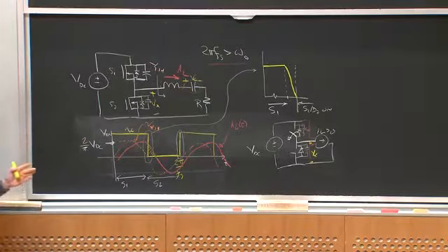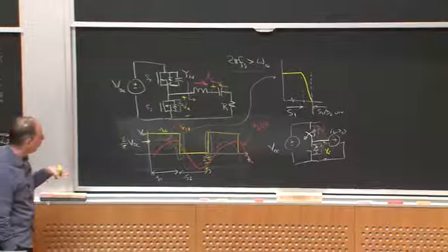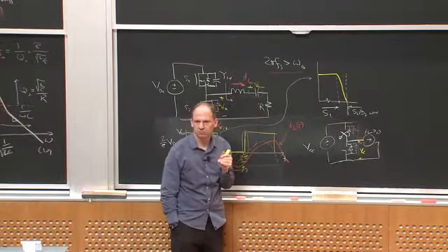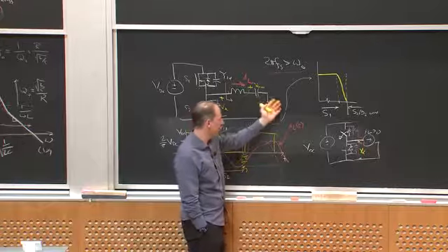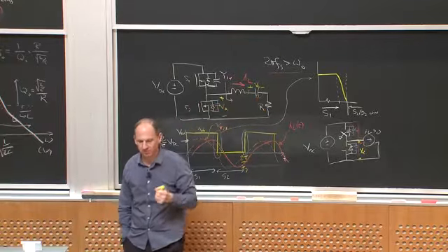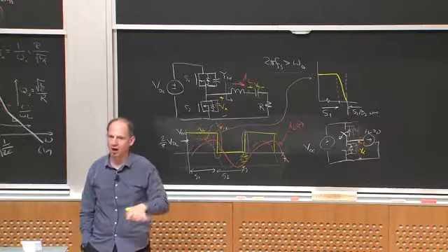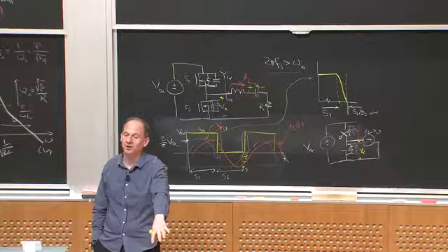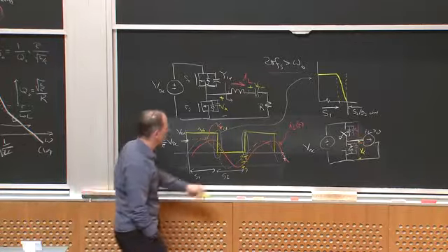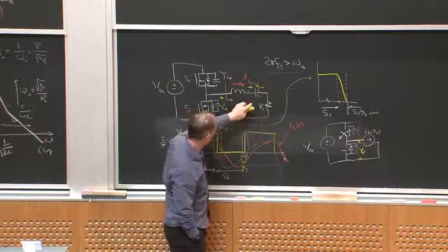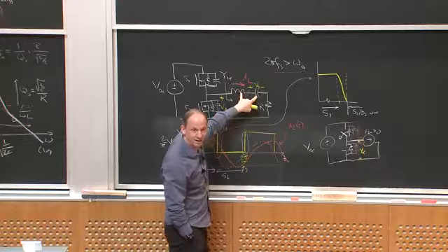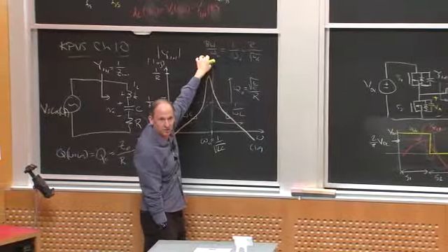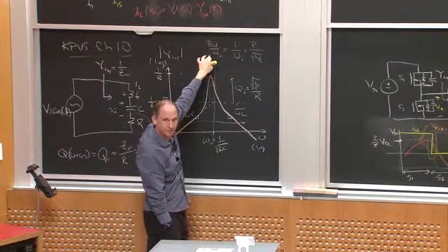But here's a challenge. Suppose now I don't control this resistor very well. Okay, if this was an induction heater, the equivalent resistance I might see might depend upon the thing I've put on my network to heat, right? How much energy I'm going to dump into it, right? If this resistor gets too small, the quality factor of the network gets really high, and then I better stay away from resonance, otherwise I'll get huge voltages on my components, on my inductor and capacitor, okay?